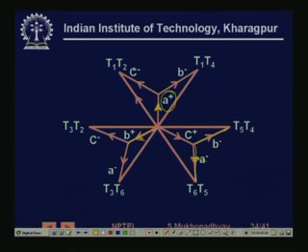When you connect A plus and C minus, because current is flowing in through one and going out through the other, the net MMF is along this direction. If you now switch off C minus and you excite B minus keeping A plus on, then the MMF will switch in this direction. So, you have made the MMF switch. As the rotor is rotating, you also make this switching such that the stator MMF, previously in this direction, when the rotor has moved, will now go into the other direction.